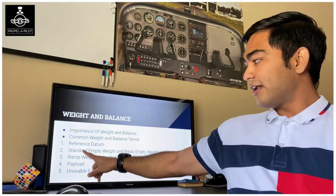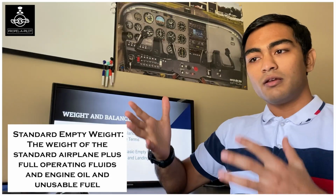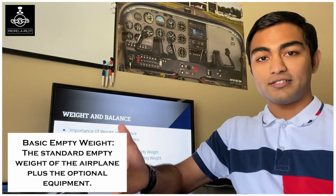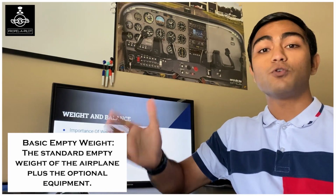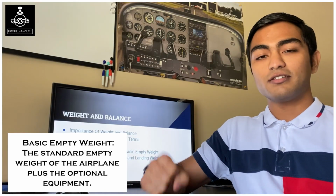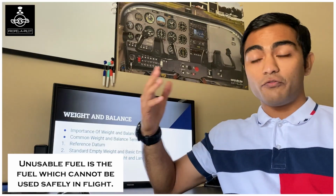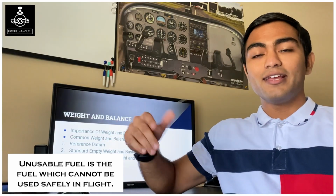Then we have standard empty weight and basic empty weight. Standard empty weight is the weight of the airplane as manufactured by the company. This is the standard aircraft. Basic empty weight of an airplane is the standard airplane plus optional equipment, unusable fuel, and full operating fluids including the engine oil. Basically, standard empty weight plus unusable fuel, optional equipment, and operating fluids. When we say unusable fuel, it is that small quantity of fuel in the tanks which can neither be drained nor used safely in flight.